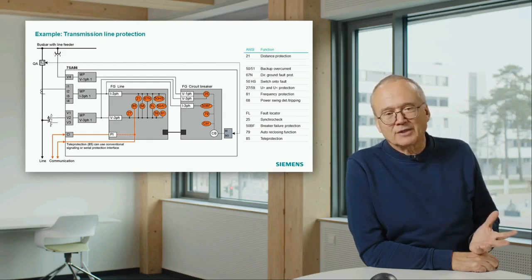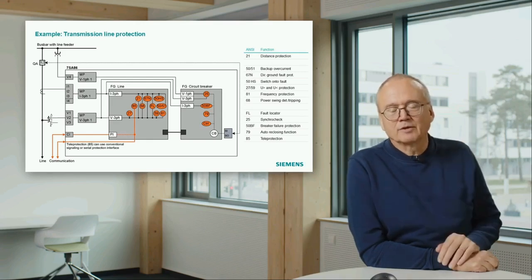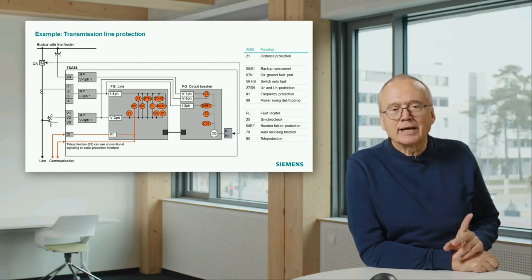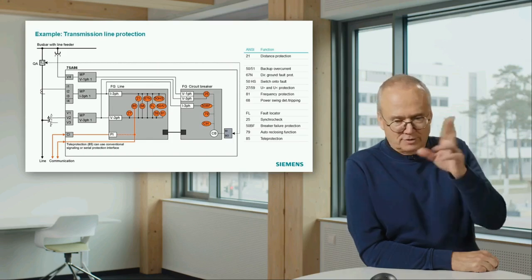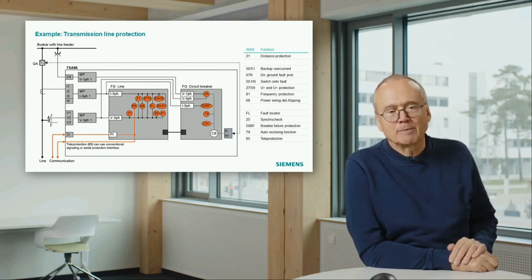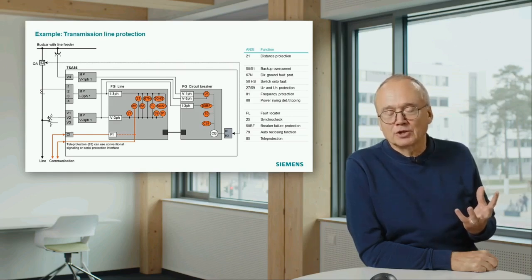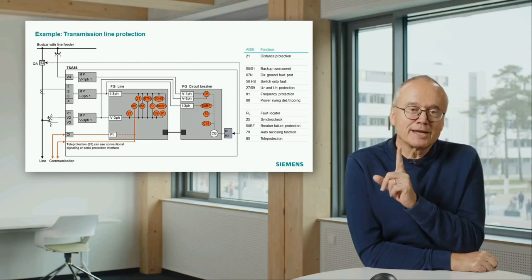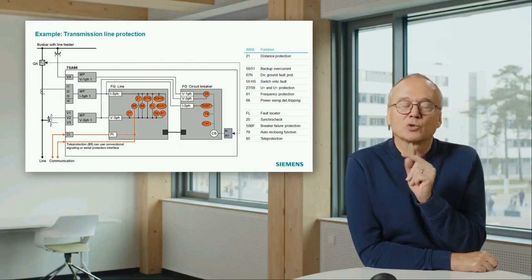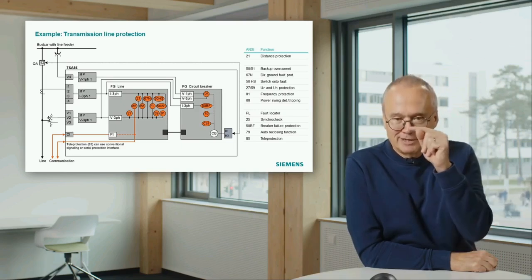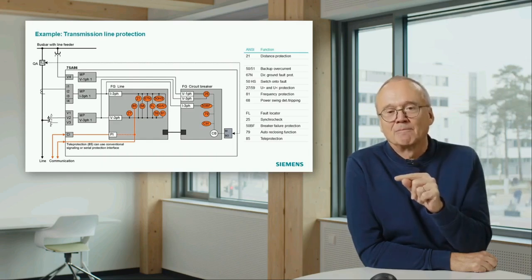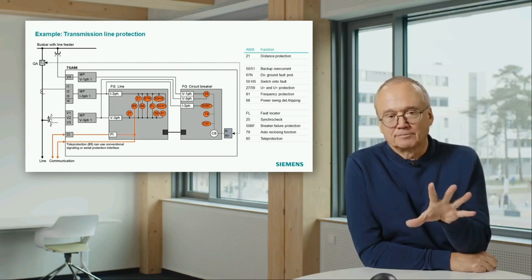You make a short circuit there for whatever reason, and that means suddenly the relay loses the voltage because you have an MCB there and that will trip the voltage input, and then you suddenly see zero voltage. And now zero voltage means to calculate the impedance, you divide zero by a current, and the result is zero. That means you measure the impedance zero, and that would trip.